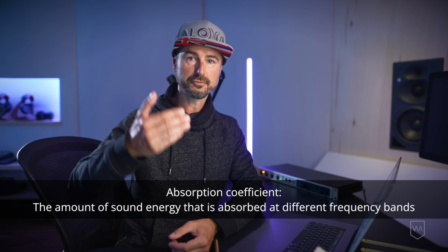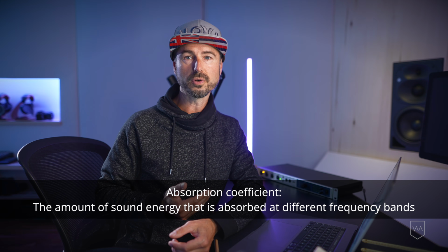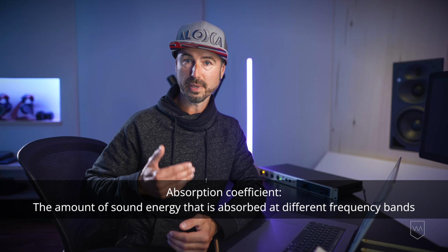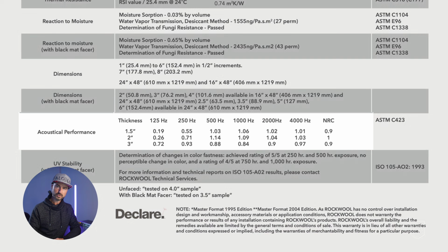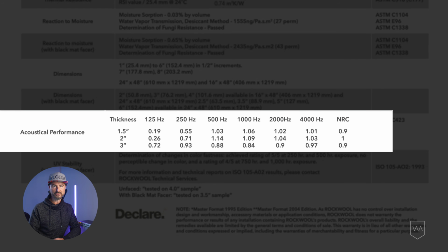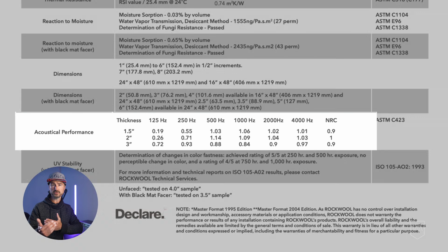We are going to use a front layer of 2 inches of Rockwool cavity rock, followed by 3.5 inches of Rockwool Comfort Bat, which is a much more readily available standard material that you see in places like Home Depot. That's 5.5 inches of total depth, because the frames that we're building this inside of are 1x lumber, all 1x6, and dimensionally 1x6 is actually 5.5 inches by 3/4 inches.